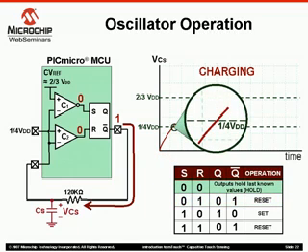As the voltage across the sensor cap increases, it eventually surpasses the 1/4 VDD threshold, the non-inverting input voltage to comparator 2. This causes the output of comparator 2 to go to 0. Referring to the SR latch truth table, this condition holds the last known output value on the Q bar output at 1, and the sense capacitor continues to charge.